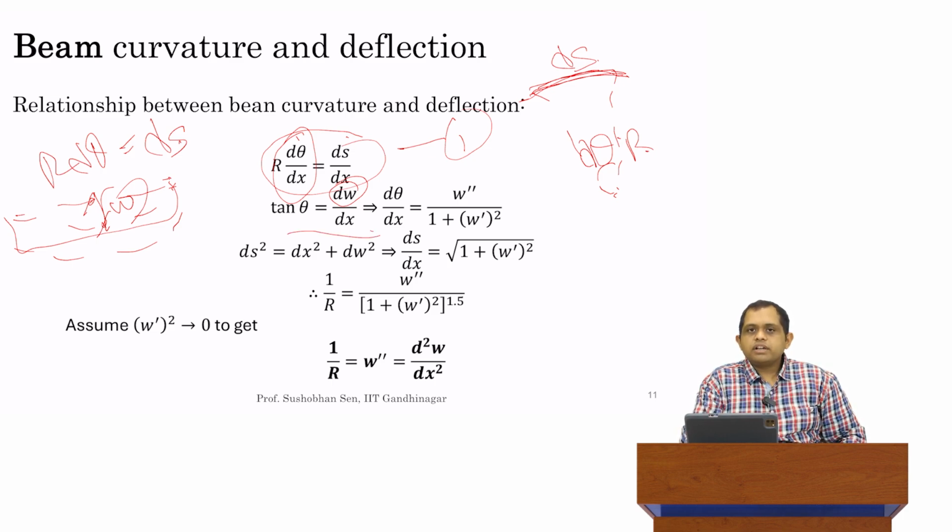By the way, the only reason we are able to make this assumption is because we assume that this plane section has continued to remain plane, that there is no warping or any sort of non-linearity in this section. So this section which I've highlighted here is also a straight line, or plane. Because of that assumption, we can write out this equation: tan theta is equal to dw over dx.